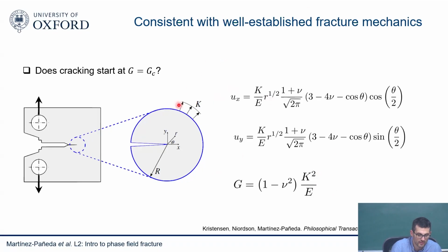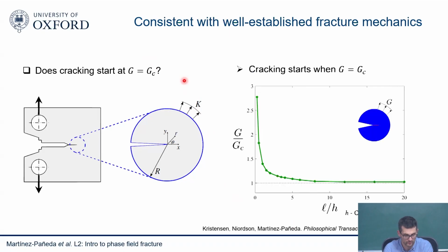So then if I apply this K field, what I want to see basically is, okay, that's actually when I do phase field. Now let's simulate the same problem. So people do this all the time, right? They apply a K field and they look at the stress fields and so on. Now we're going to solve the problem with phase field, and we're going to see, okay, will crack growth occur when K equals the toughness, or in other words, when J equals the critical energy release rate? We'll do that. G equals the critical energy release rate. And this is what you see.